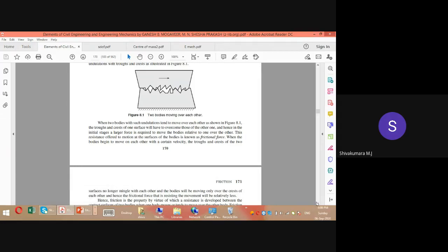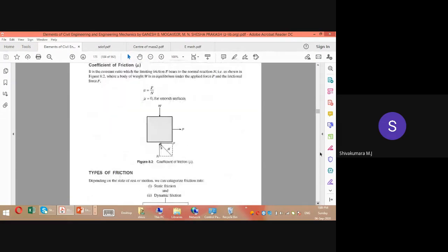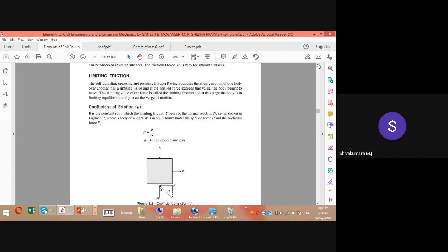So in our mechanics subject, we'll discuss dry friction. Before going to that, we need to be aware of limiting friction and coefficient of friction. See, the magnitude of a frictional force, for example, I have kept a block on a table. I'll apply 5 Newton of force and the object is not moving. Under this case, what is the magnitude of developed frictional force?